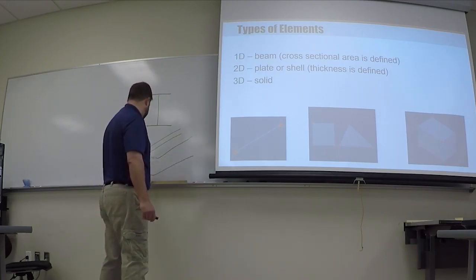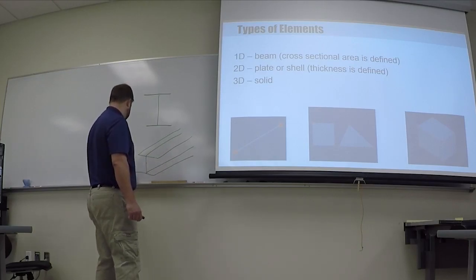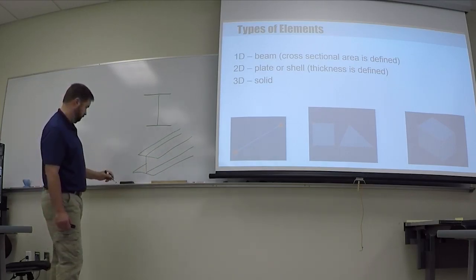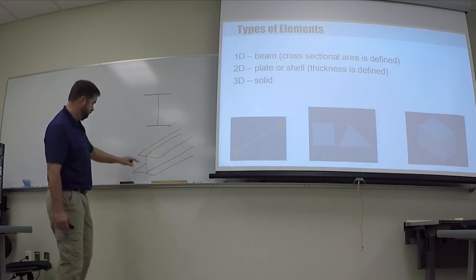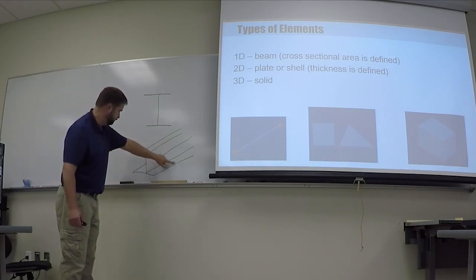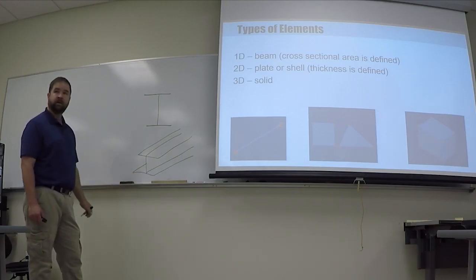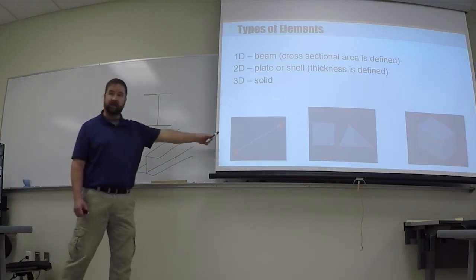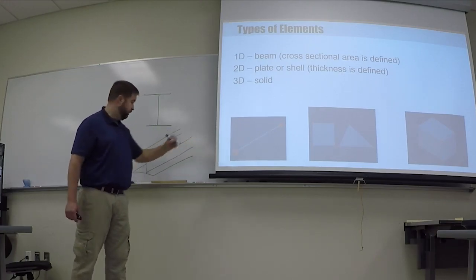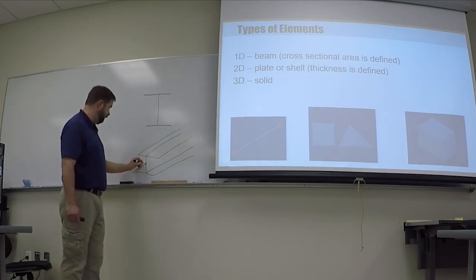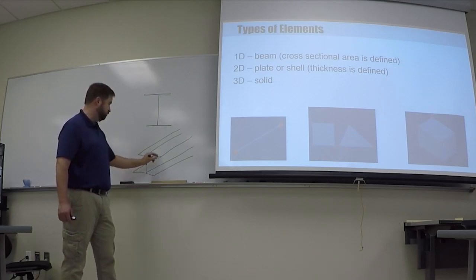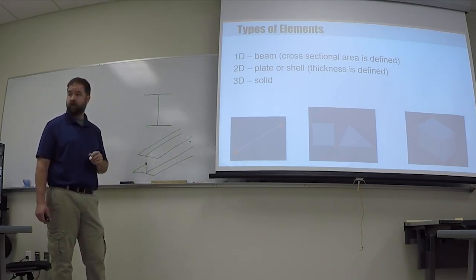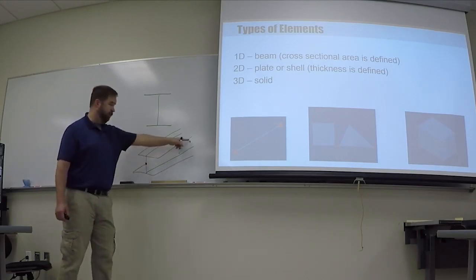Okay, so there's my I-beam, right? Does that look about right, isn't it? Trying to do an isometric on an I-beam. And so if I was to model this as a single one-dimensional element, then this could be nothing more than the node starts here and it's a straight line going back here to wherever this beam ends, right? Could even do one element.